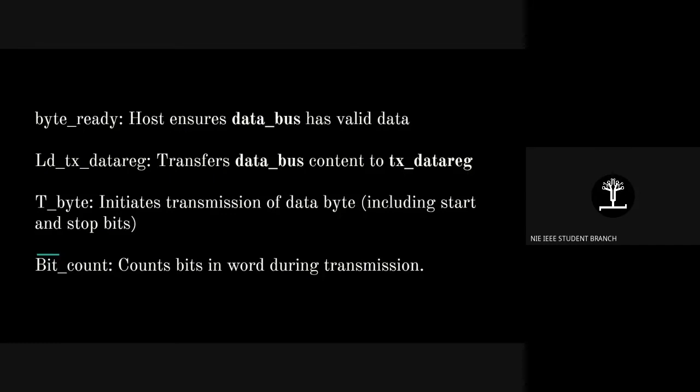It all depends on timing also. When do you want transmission to start happening? From the data register, whenever you want to start shifting it outside, you put it into a shift register, because that is what shifts it towards the right side. We are doing right shifting here, towards the LSB. Let's say the data is 1011101, something like that. The rightmost bit, that is the LSB, has to go first. The LSB gets transmitted first, and later the other bits.